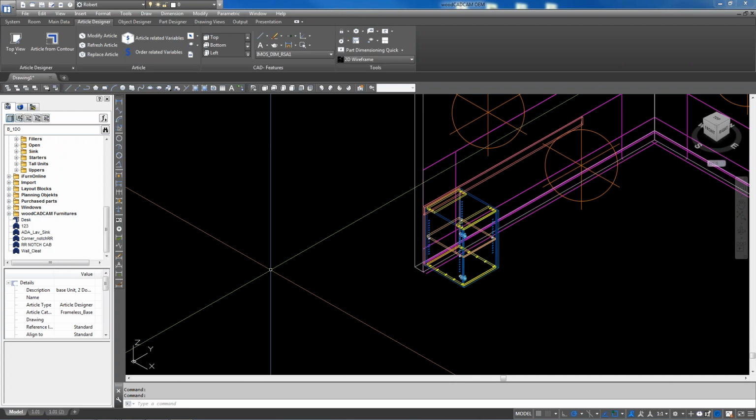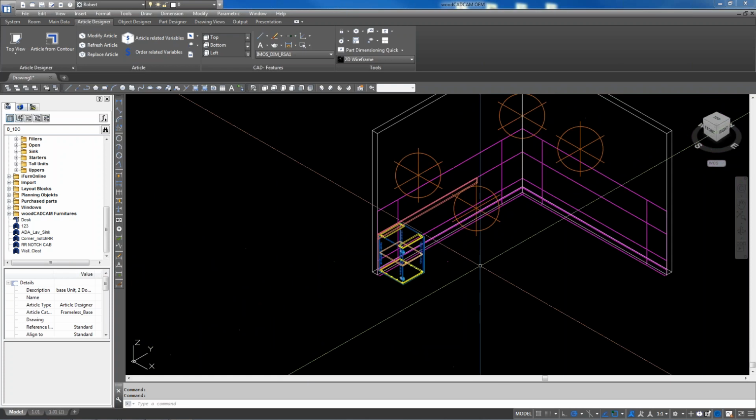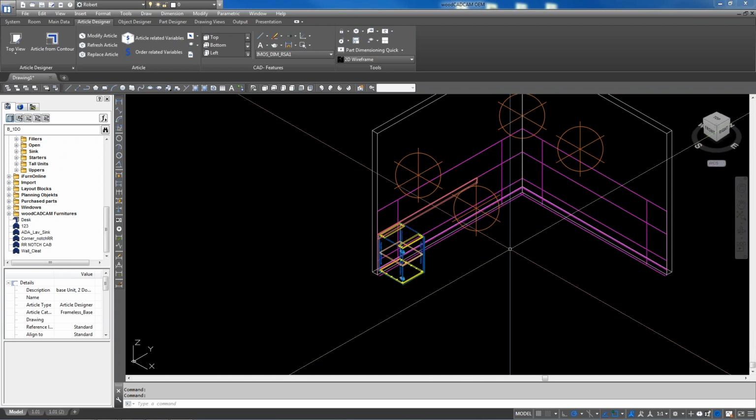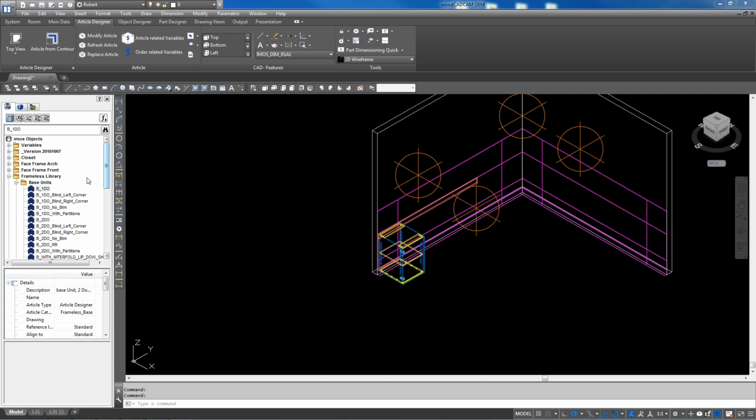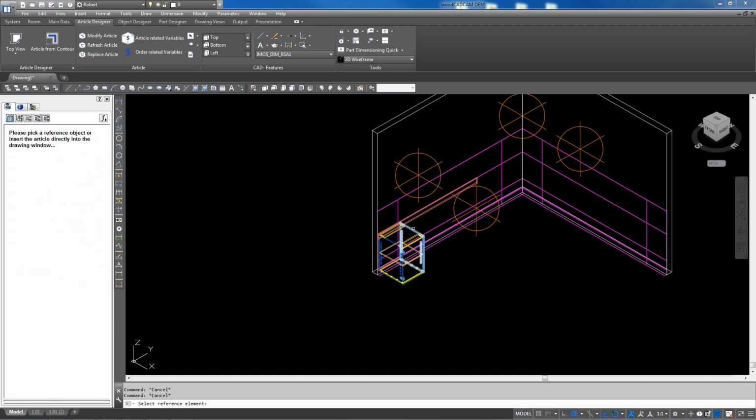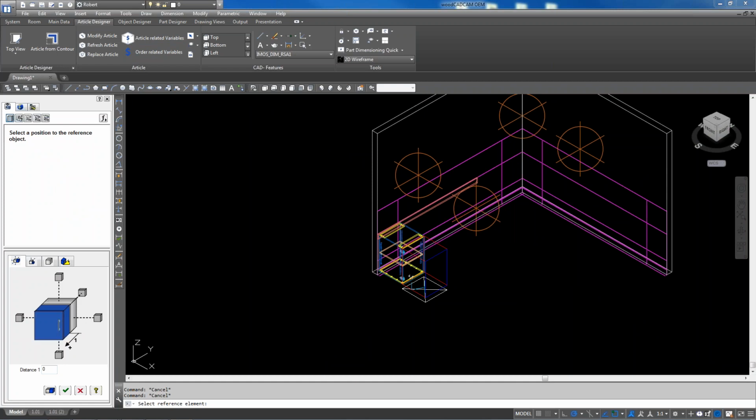Let's say we have base cabinets, and between them there is a refrigerator 24 inches wide. That refrigerator has a separate base, and it needs ventilation on the bottom. So we need like 3 slots. Usually we do, if I'm not mistaken, half inch, and about half-inch spacing between them.